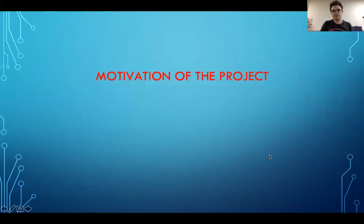What's the motivation of this project? This project tries to create a way to individually control the frequencies of the spin Hall nano-oscillators in a big array or two-dimensional arrays, and individually control the on-off states of the SHNOs in the two-dimensional or one-dimensional big arrays. Because to use these spin Hall nano-oscillators in neuromorphic computing, we need really complicated big arrays, but we cannot control the individual frequency and individual on-off states yet.